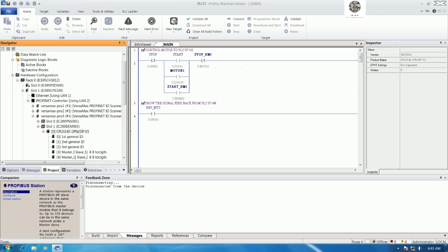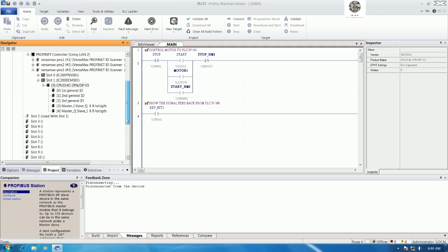Last time we had only 2 with byte memory. Master I slave Q means that PLC GE is input and PLC S7-300 is output, and for 8 byte more, master Q slave I means that PLC GE is output and PLC S7-300 is input.